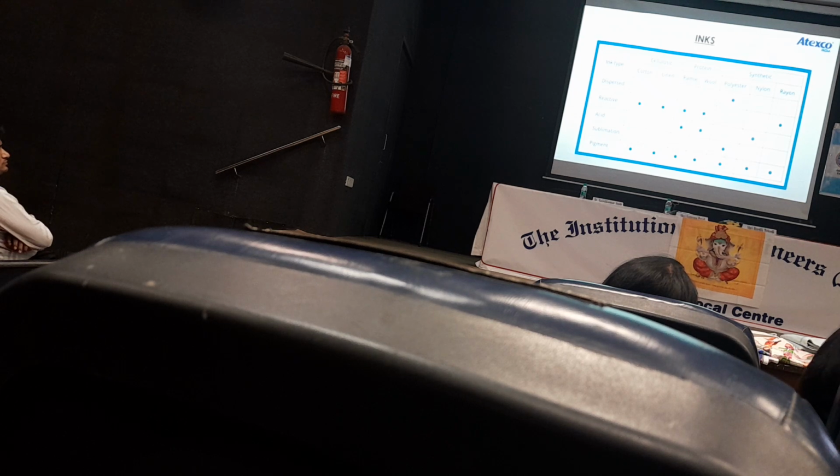But in sublimation printing, we print on paper and then fuse. This is the sublimation ink. And disperse is a pure water-based ink. In that case, we have to do the whole process from first to last: coating, printing, steaming, washing, all processes for disperse. But in sublimation, there are only two processes: paper printing and transfer. With pigment, we can print all fabrics.